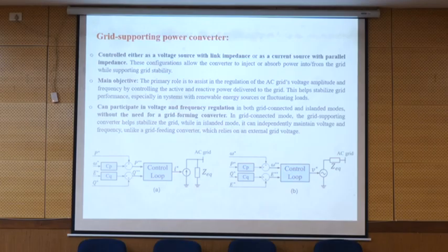And for the reactive power is also the same. So later we see, I mean, I didn't go through the mathematical equation, but later we see that equations that, you know, when we have delta Q, or a reactive power change, is equal to a constant value times delta V, because we can control the voltage based on the reactive power.